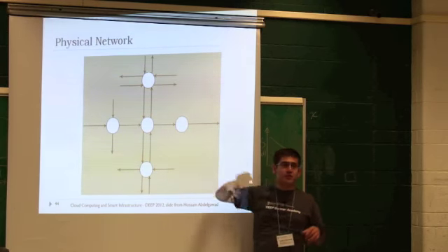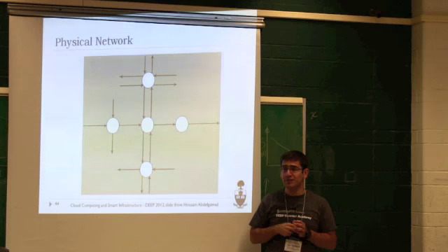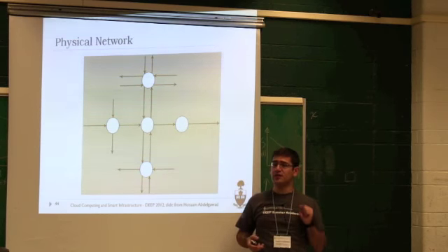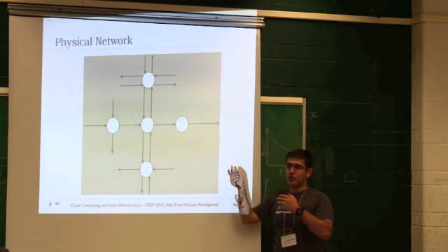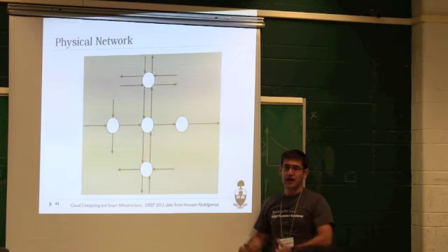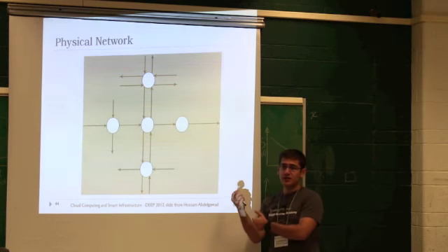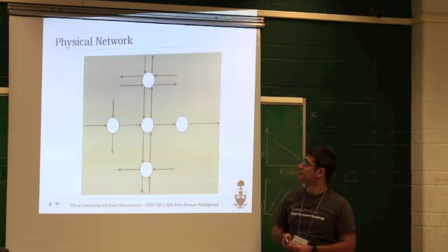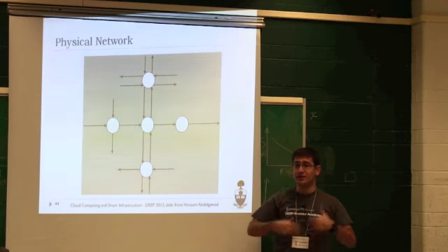If you have ramps, you would have a smaller speed limit on the ramps, all of those things, as you can see them on Paramix. Okay? So now you're going to learn how actual traffic engineers program these things, so that tomorrow when you're using Paramix, you'll understand where these are coming from. But you're basically using whatever has been worked on quite a bit, and then you're changing stuff in it.